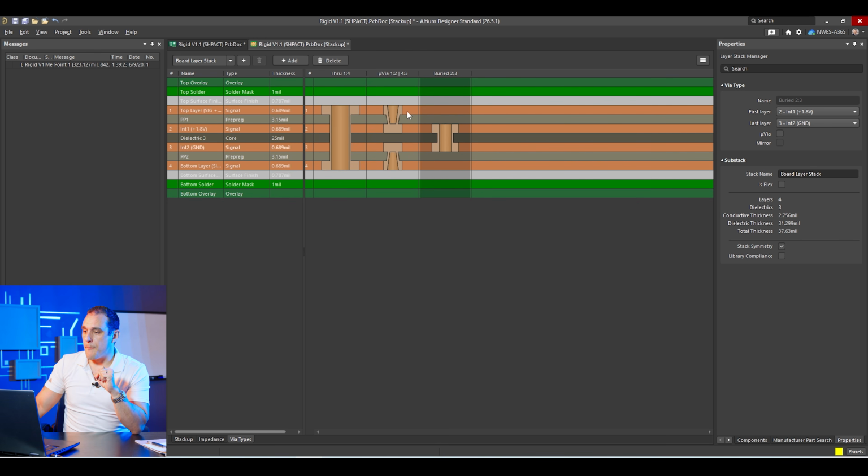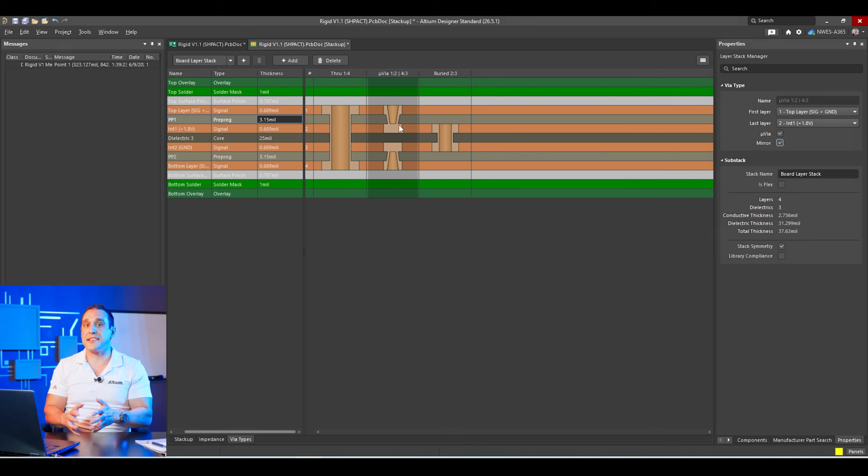Now, if we're going to be using microvias on the outer layers, how does that impact the thickness of this outer prepreg that we would use in this design? Well, we can use this 3 mil thick prepreg if we want. We just need to make sure that the vias are sized large enough to fit within the aspect ratio requirement imposed by the fabrication capability. So typically that maximum aspect ratio is probably going to be something like 0.8 to 1. And at the very, very maximum, you might see an allowance for a 1-to-1 aspect ratio on the outer layer. So that means about a 4 mil drill is going to be your minimum allowed drill size in these outer layers if you use a 3 mil thick prepreg.